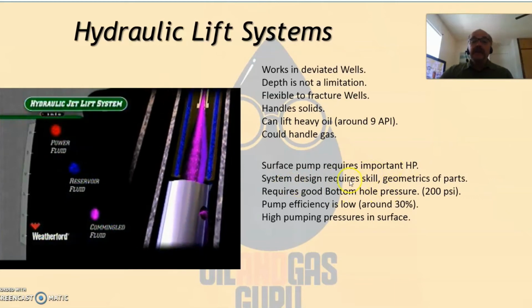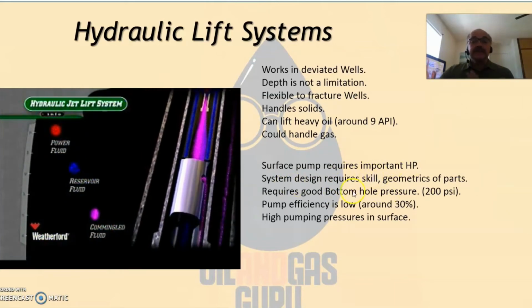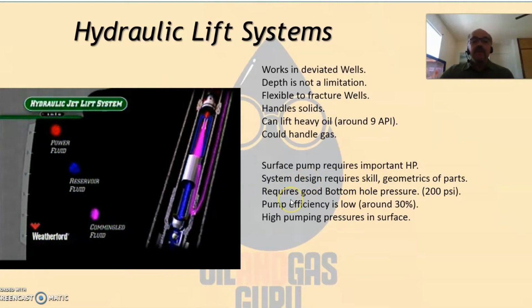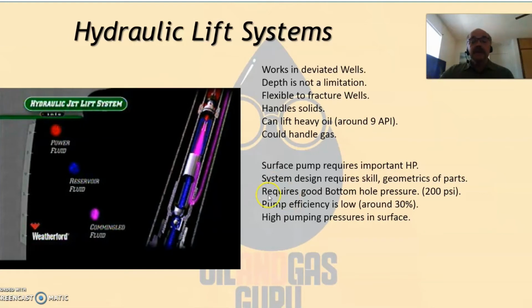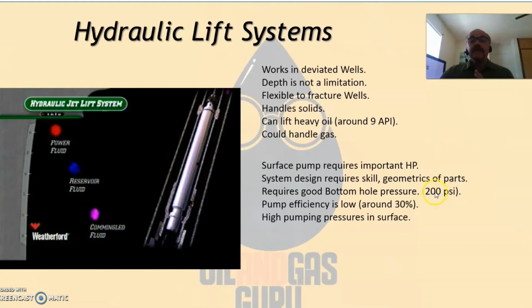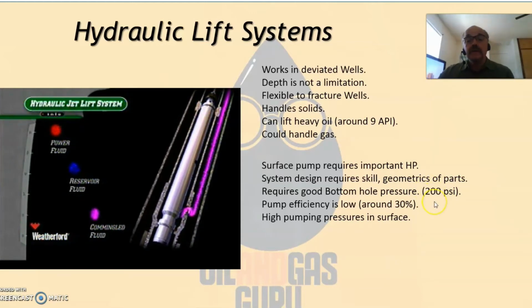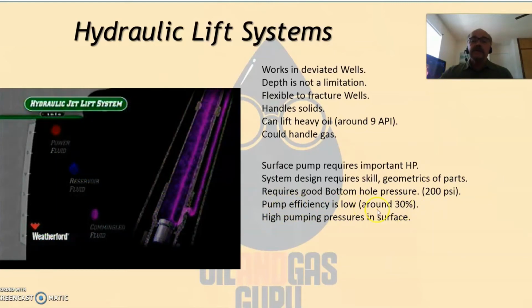We need skills, but again, the suppliers know very much about it, and we need to know how to talk to them and discuss the details, okay? It requires a not very low flowing bottom hole pressure, so if we need to go very low, maybe this won't work. And the pump efficiency is very low, 30%.